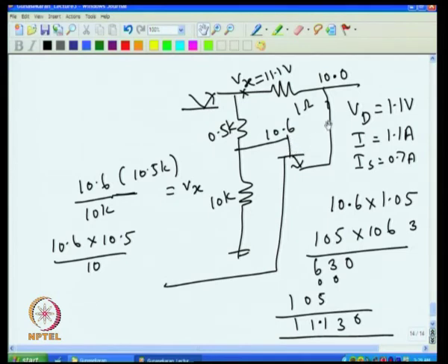because this is 10 and if there is no current, this is also 10, and this is not going to be 10, this is going to be around 9.5 volt, the voltage at this point is going to be 9.5, this is 10. That means this is 9.5, this is 10, means this is already reverse biased. So, the voltage across this transistor in the normal working condition applies a reverse voltage. Under short circuit condition the voltage across this is very small, because the 10 volt had disappeared and here also it had disappeared.